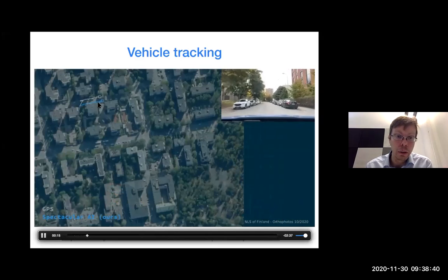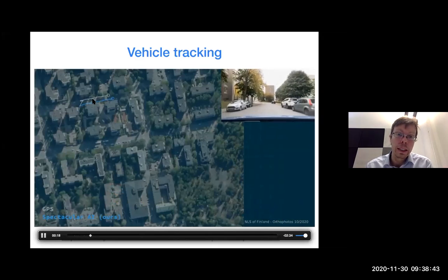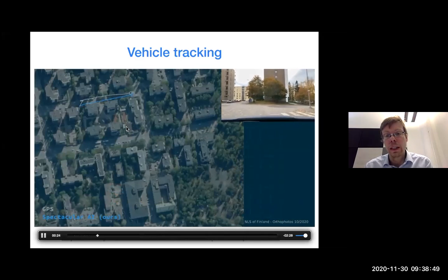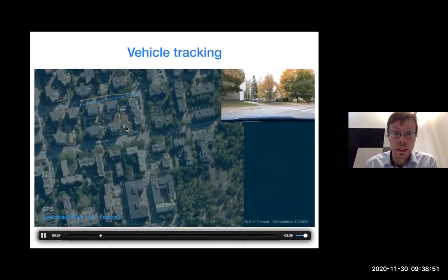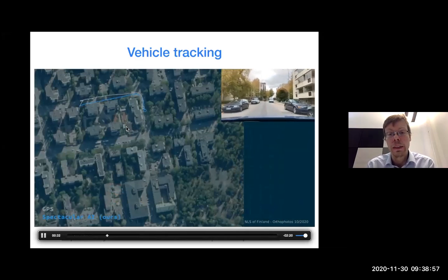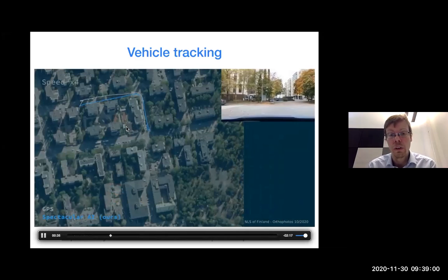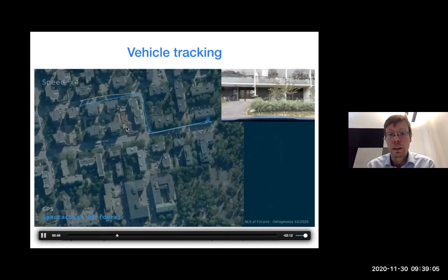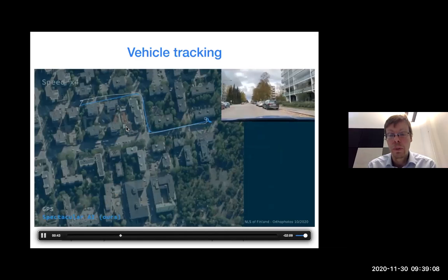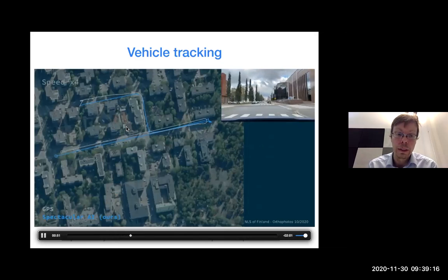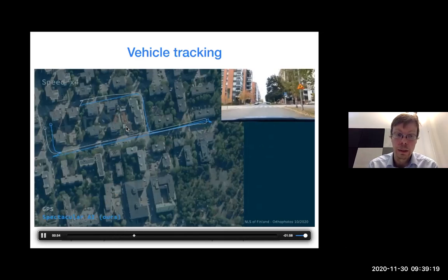And here these phones are now placed on the car, and what we show here is the trajectory estimated by our method, which is the blue curve, and the gray curve is the GPS-based ground truth. So in this kind of an outdoor setting, GPS works quite well, at least in this environment, and it does not, of course, suffer from the kind of long-term drift that sequential methods may suffer from. So our approach does not use the GPS as a measurement at all. So it's only based on the camera and the inertial sensors, and it runs real time on the smartphone.